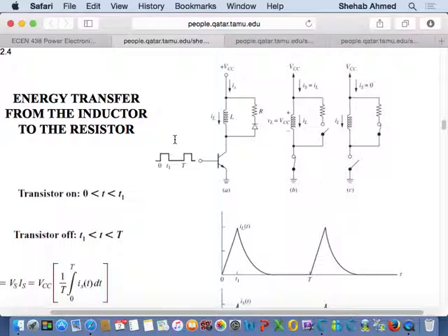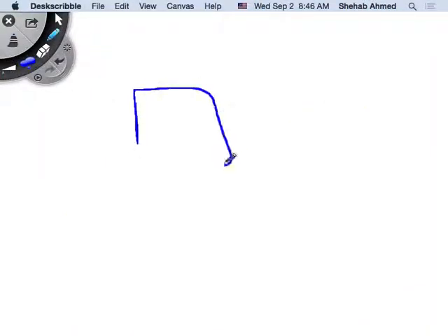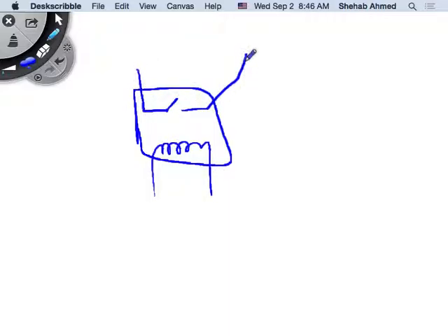And you use that all the time. For example, if you want to turn on lights for the first time in your life with a microprocessor, right? You want to impress your parents. I'm sitting here and turning off the lights. You would basically put a relay in series with the light circuit. So you would put a relay, and this relay would be a box like this. Just a simple box, and it would typically have an input that is sort of an electromagnet, and this electromagnet is actually driving a mechanical switch here. And this would be your light bulb, for example. And then you will have your AC source here.